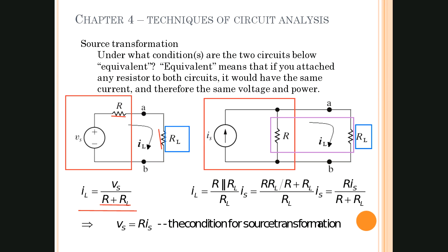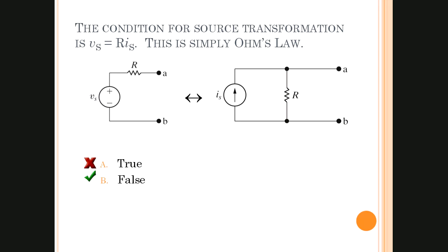And so basically we're looking at a voltage divider or a current divider circuit here. But the whole point of transformation here is to prove, and we can plug in values into these later, that it would be the exact same thing. Whatever that voltage and resistor in series would be equivalent to that same current source and that resistor in parallel. And that's going to actually make it easier for us to do circuit analysis, and we'll see that in a couple of slides.